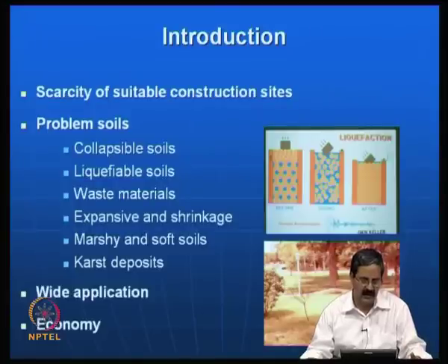These liquefiable soils are essentially sandy soils, which have a tendency for liquefaction, meaning they behave like a liquid under the influence of impact loading like an earthquake. You can see the condition before an earthquake occurs, and then during the earthquake event, which is about 30 seconds to 1 minute, there is a particle rearrangement, and the foundation that we have at the top could sink in.